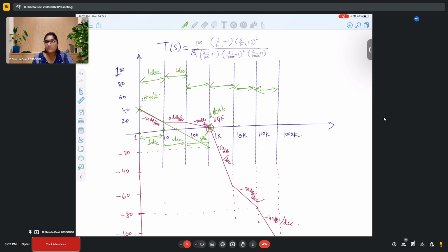Yes, the only complication comes when there is a pole or a zero at the beginning, and then you have the first pole or zero, but you find that your crossover frequency has already been met. So in that scenario, it's a bit tricky. But thinking from an academic perspective, that will never happen, because people who design the problems keep these things in mind already. But practically, how would you solve this issue? Let's say practically, also, it's very rare.